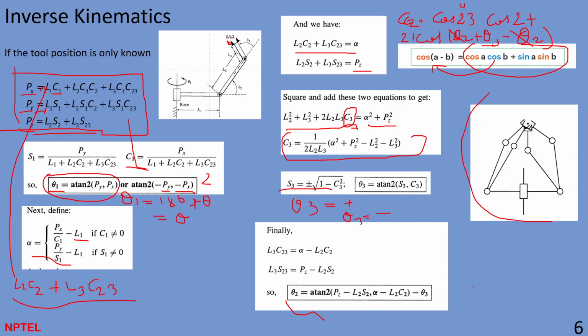So in inverse kinematics, if you know the position, there are multiple solutions for this question. See that there is this theta 1, let's say 0 here. Here it is, let's say 180 degrees. So using this method, you can reach this position by different means. You see the orientation is quite different here. In one case the orientation of the bar is something like this, and when you go like this, the orientation looks different.